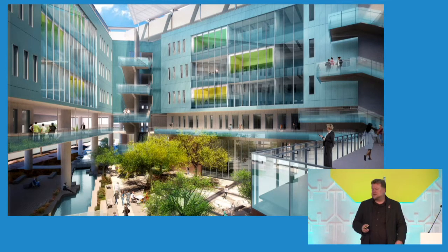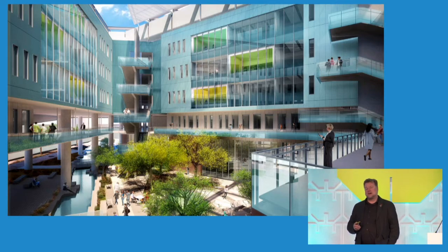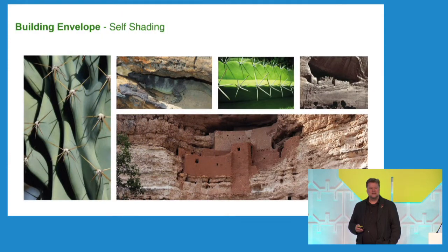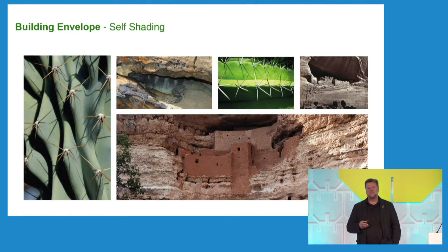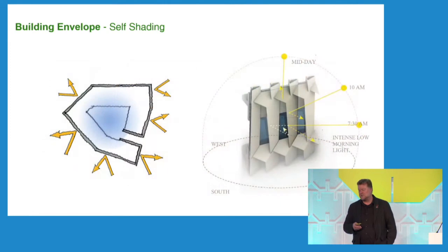And indeed, the entire building has hardly any forced air cooling. It's all through chilled beams. Obviously, the skin itself is all about performance and how it works, and so again, we wanted to create a skin that was self-shading and performing. It's a performative approach to design. And so we developed this approach to the skin, and of course, every facade has to be considered differently because each one performs in a different way. Each surface has a different aspect to it, so every elevation is different because it performs and responds in a different way.